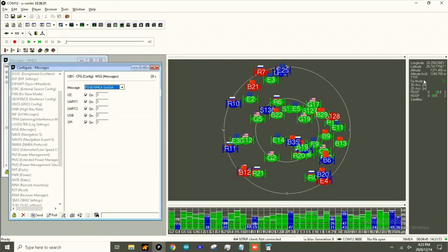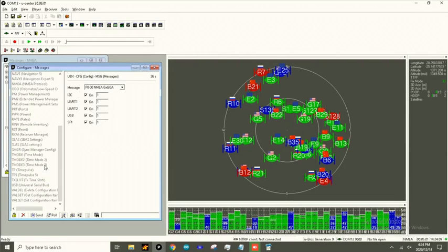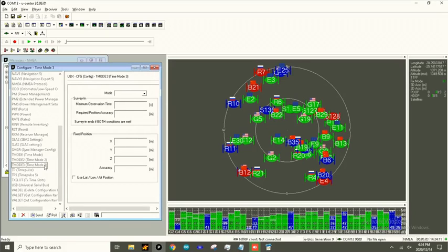So first, the simple way to survey in our antenna. You'll see on the top right hand corner, this is the approximated position based on the available information of the GNSS receiver. One way in which we can do this surveying is taking the average or the mean of multiple of these readings and minimizing our errors, which can be thought of as a sphere surrounding the receiver, a volume of uncertainty of where exactly that receiver is positioned on the Earth.